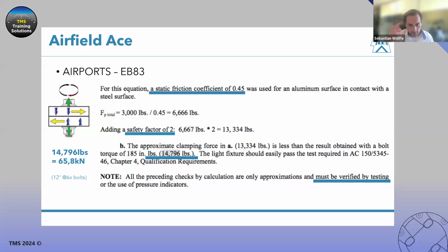So if you go back to the first slide, where I did the rough calculation with values of 0.1 and 0.3 as friction coefficients, we end up achieving in lab circumstances a maximum of 4 kilonewton per screw, or if it's dry, just 1.334 kilonewton. Okay, so next.